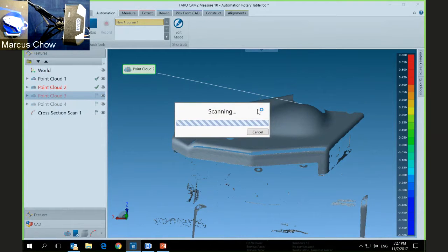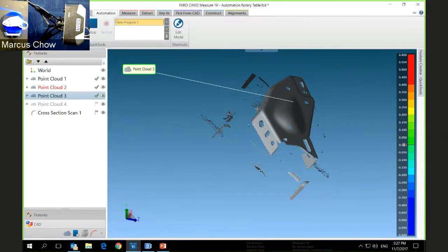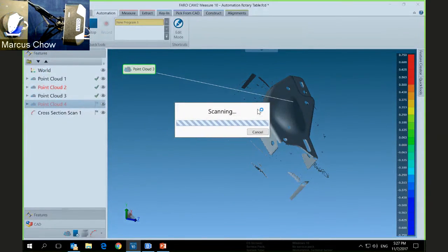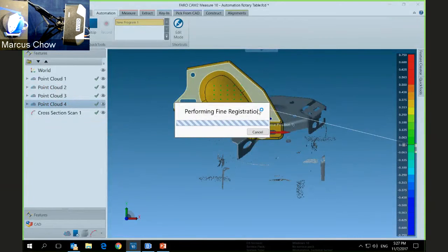As you can see, there is blue light being projected onto the part, and this light is reflected off the part and captured by both the left and right camera. So the advantage of using blue light is that whether or not it is a light or dark surface, matte or glossy finish surface, you'll be able to scan this part by just setting an exposure setting for the cameras located on the Cobalt. So that's something that I will show you in the second part of this demonstration.